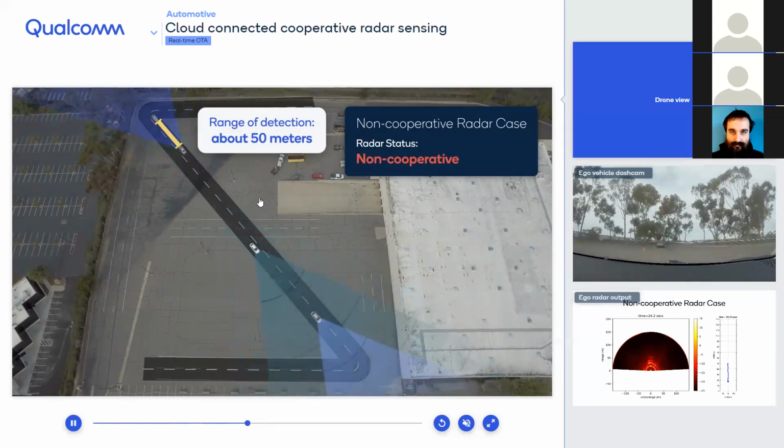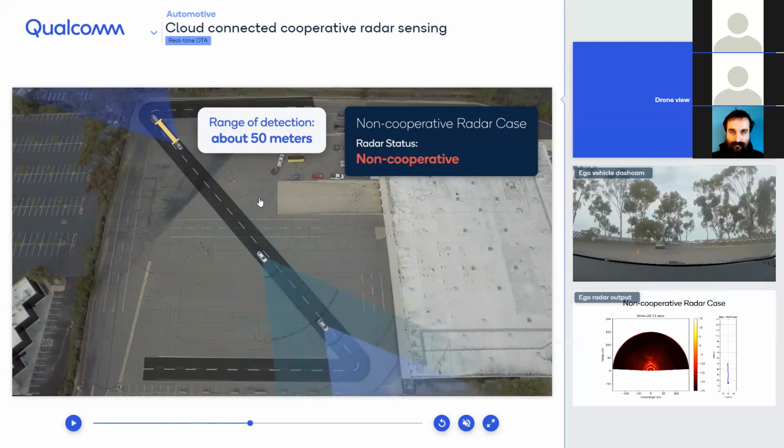Right. So maybe one of the highlights that I would like to make after this is that interference is bad for the radar receiver, and it's bad in two ways. It either creates a ghost target, which means that it's not a real target. It's just because it's transmitting some blocking signal to you, and then it appears to be a target. So it's a ghost target. Or it can jam your radar receiver so that you cannot receive any target, which masks the real target. So that is the two ways that interference works.